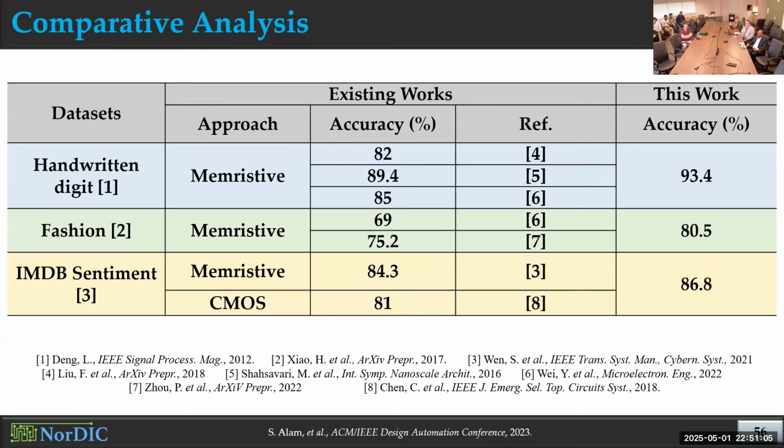So after storing the weights, when we try to perform the matrix vector multiplication, we optimize the read operation as much as we wanted. And we made sure that we get the highest amount of distinguishability in the decision-making step. But in the memristor memories, we don't have that freedom because there we use the same path for read and write operations.